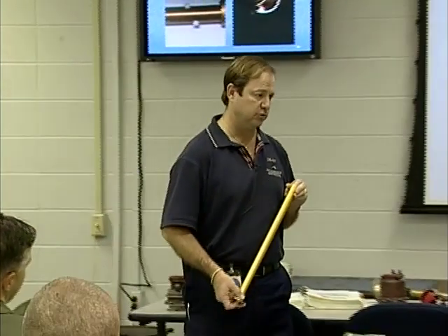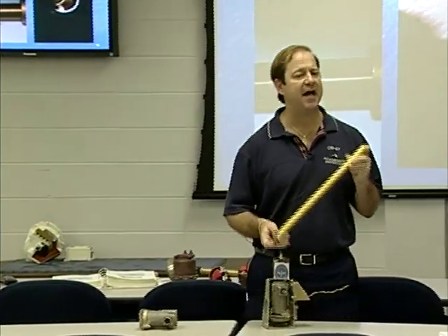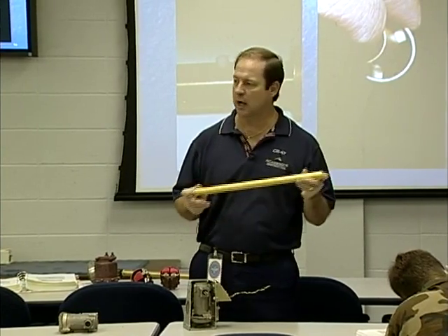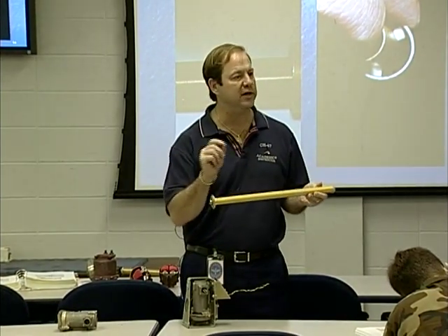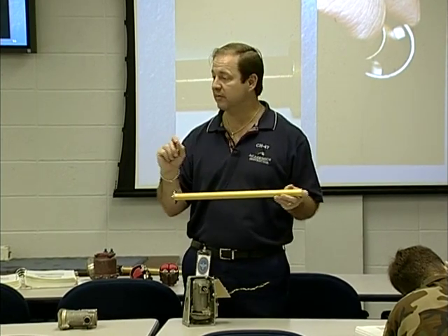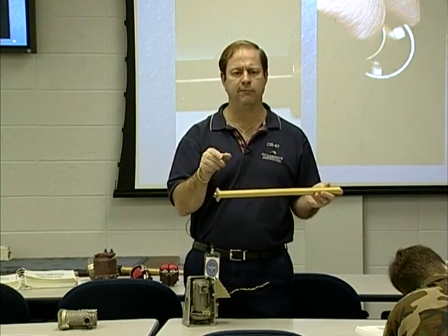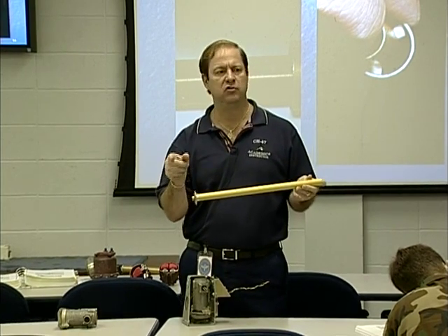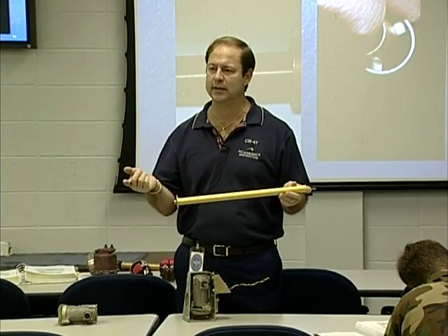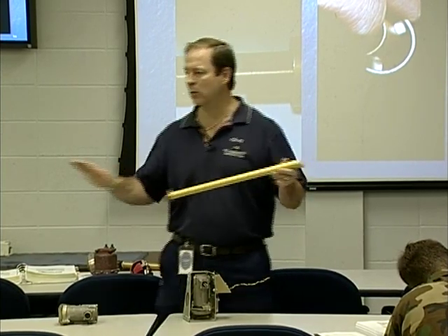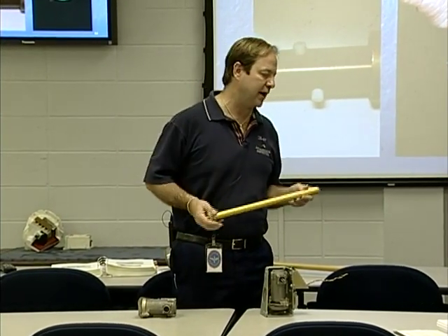Okay, it does require electricity. What else? It automatically factors in the type of fuel that you're using. So there is no reason for you to have to sit there and say, okay, I'm using JP4, it weighs 6.4 pounds per gallon, as opposed to JP8 that weighs 6.8 pounds per gallon. You don't have to do that. Because this is a capacitance type system, that's automatically factored in.